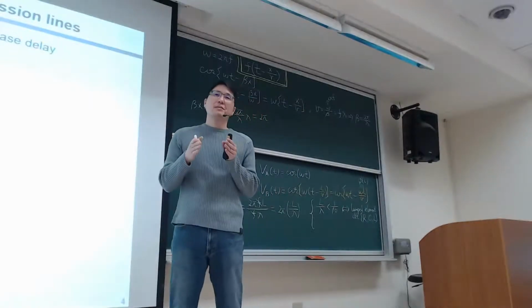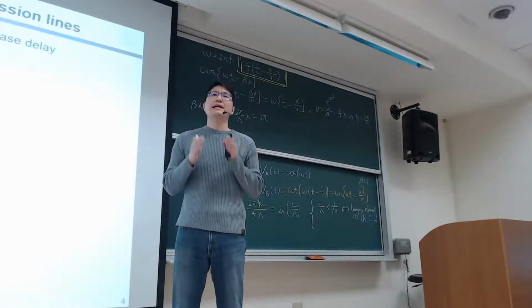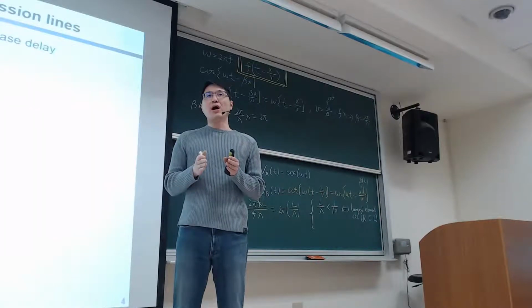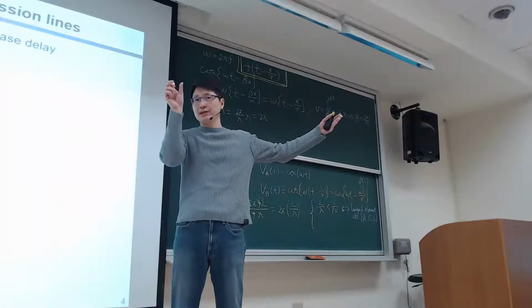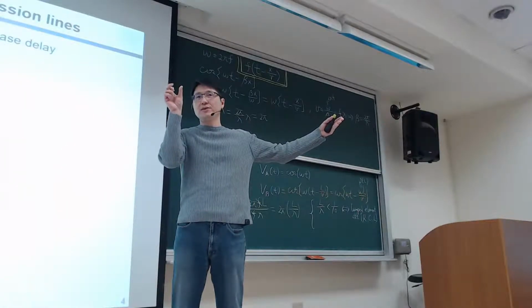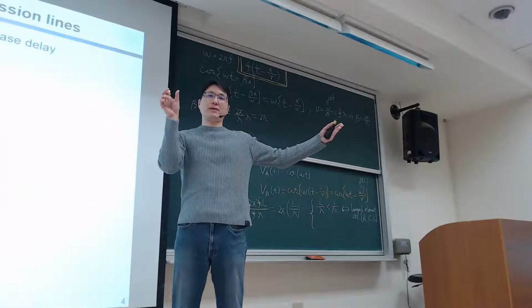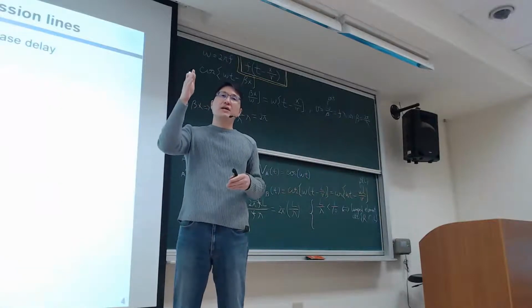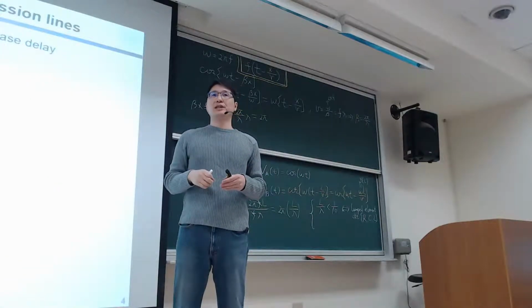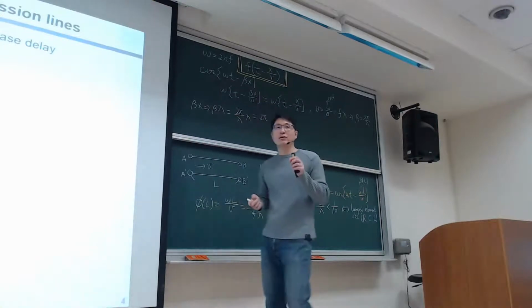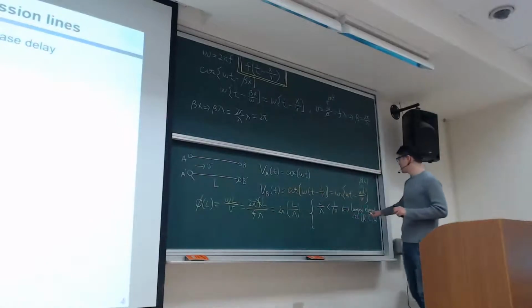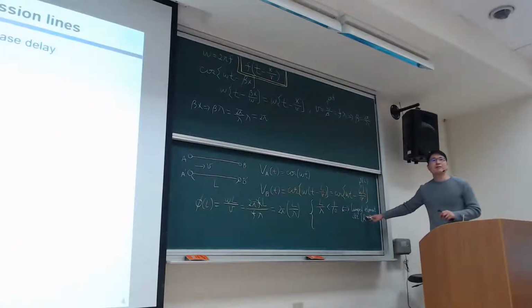The lumped element circuit is effective when your operational wavelength is very long as compared to your device dimension. So in that situation, every position on the element can be treated to have the same voltage and the same current. So voltage and current in this assumption can be viewed as constant across the entire element.